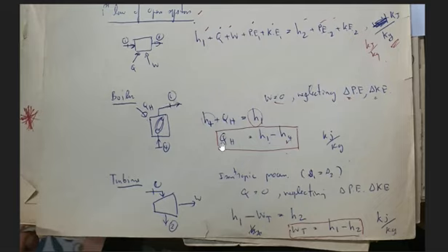So we will get QH equal H1 minus H4. If we know the status of the steam at point 1, if we know the pressure and the temperature, which we can measure, we can determine the entropy, which is the property of the steam at that point.